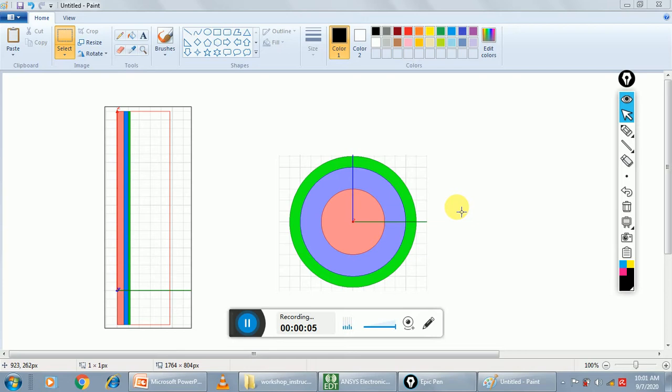Here we will determine the electric field distribution on a coaxial cable based on the potentials applied on each conductor. The coaxial cable is solved with XY representation. In the previous lecture, we discussed representation in the RZ plane, but here we discuss the XY plane.